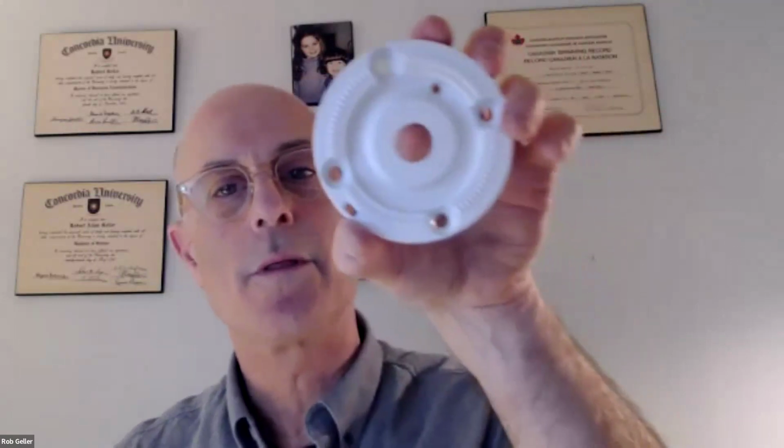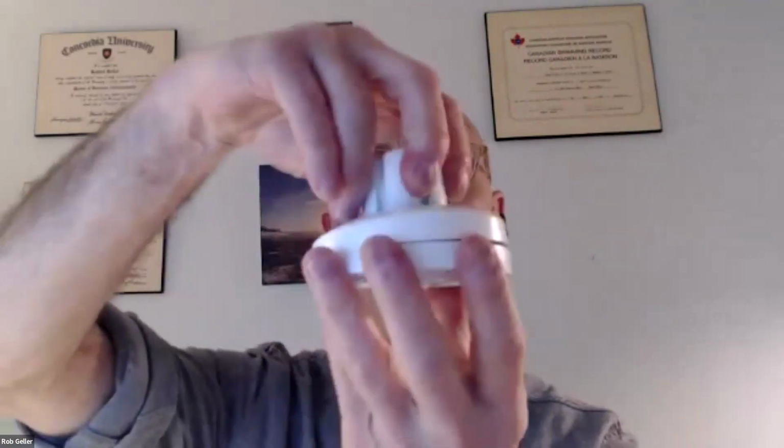So you're now offsetting the slope of the ramp. All you need to do is fasten this to whatever surface it is, concrete, with one anchor, and then you put the top half on, rotated to the appropriate setting.